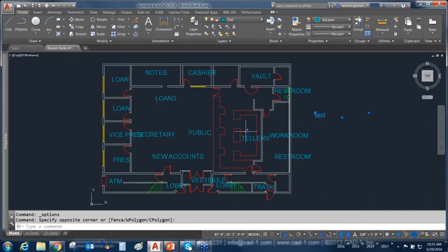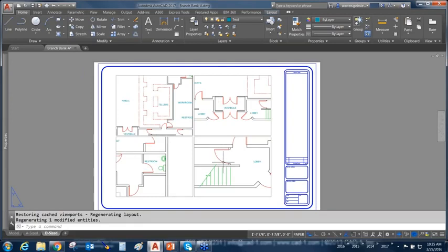It will then, in any paper space viewport, freeze and thaw the opposite layers inside the viewport. So it goes back to the old way of doing things, but it does it for you automatically. Now, if you were to take that drawing and open it in a newer version of the software, it'll automatically recompile everything and put it all back on one layer and turn it into an annotative object again. So that's pretty cool.